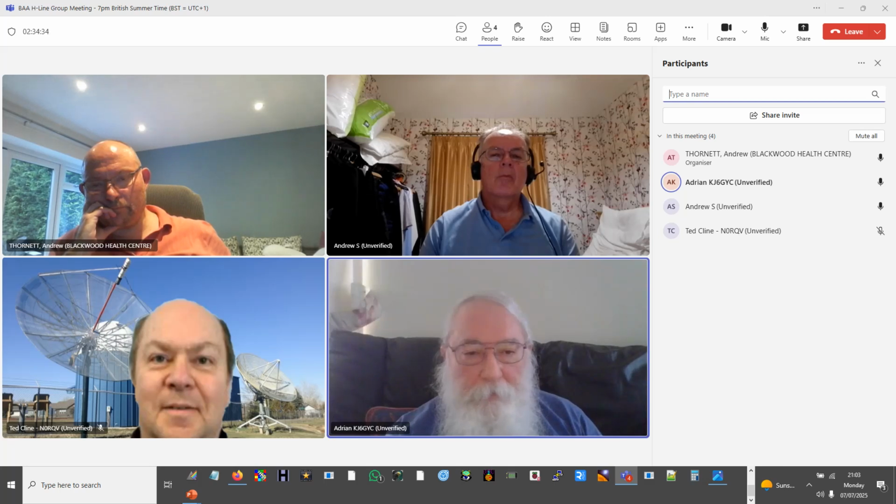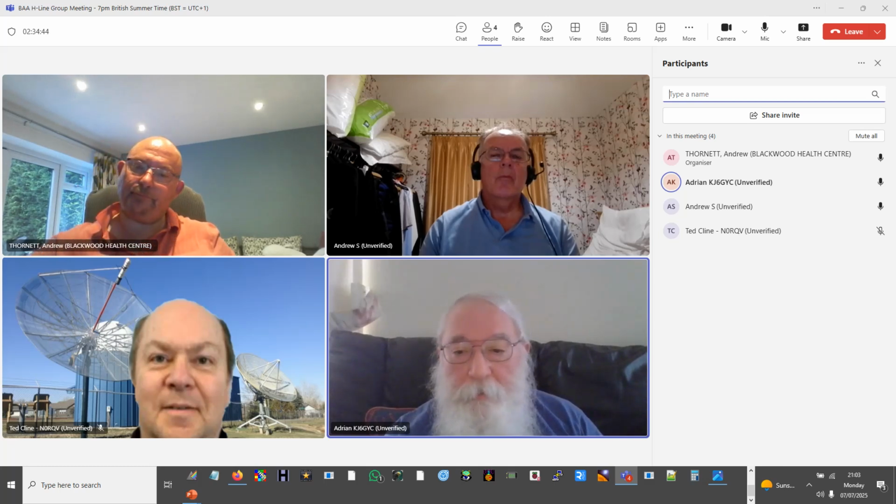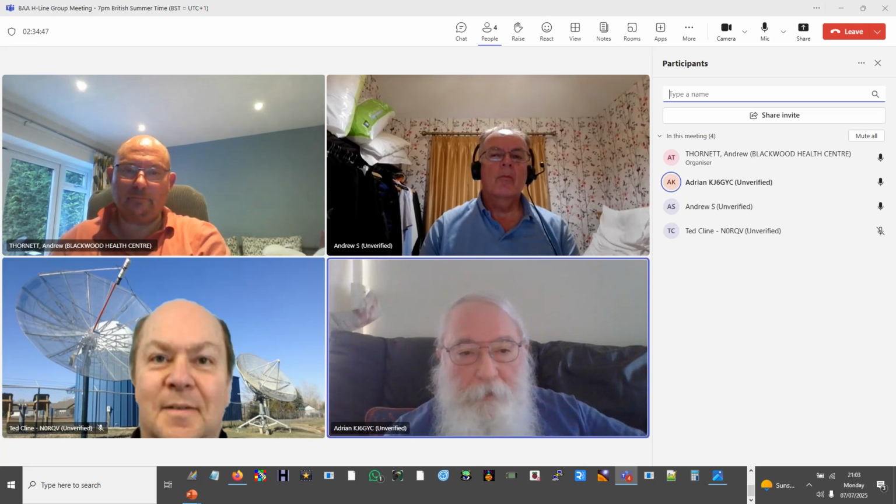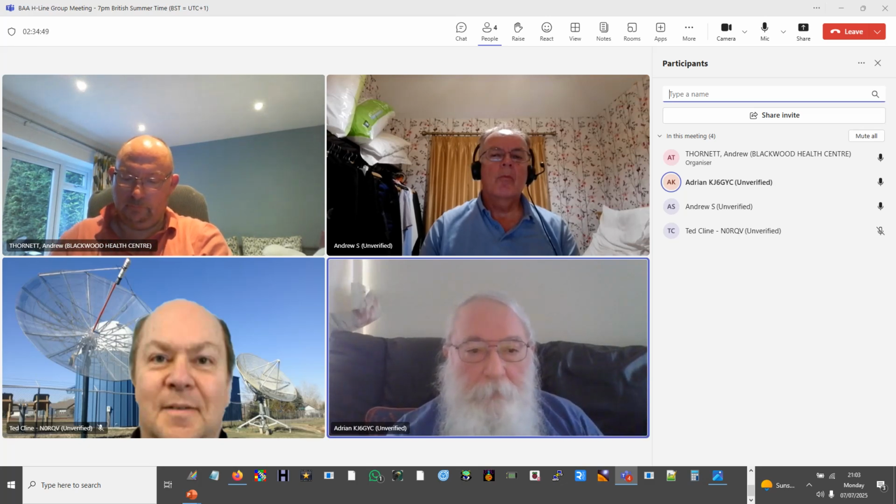You can look these up, and they'll have different voltage ranges: 5 volts, 12 volts, 6, whatever. Some of them are adjustable. You can draw a little circuit with a variable resistor and adjust the voltage it regulates to. But whatever voltage you want out, you might need something like 1 or 2 volts higher on the input side, just to cover the overhead.